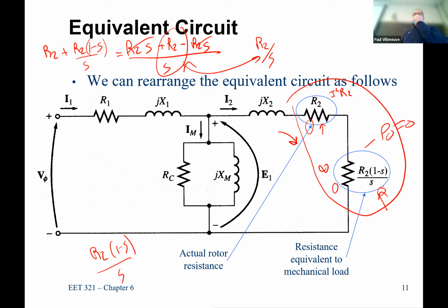So the ones we have in lab, they're rated at 1670. You can say those aren't very efficient, they're garbage. But remember in lab yesterday, we were running way over full load amps for quite a period of time. And if you had a real world machine that did that for 13 or 14 seconds, it starts to burn up, gets too hot.